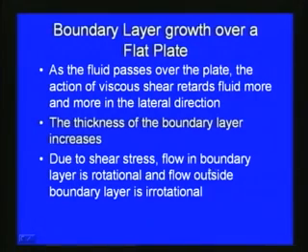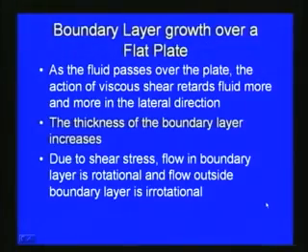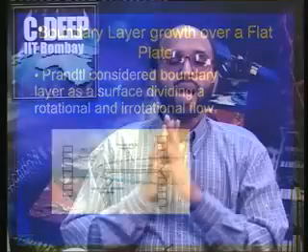So, due to shear stress, flow in the boundary layer is rotational and the flow outside the boundary layer is irrotational, and as the fluid passes over the flat plate, the boundary layer thickness keeps on increasing depending upon the problem. Like this we can define the various aspects of the boundary layer growth and how the system is behaving.